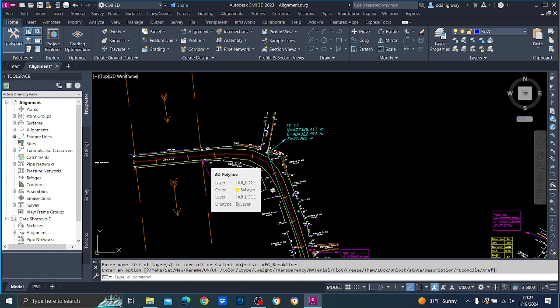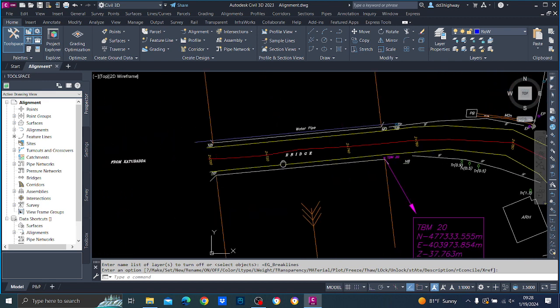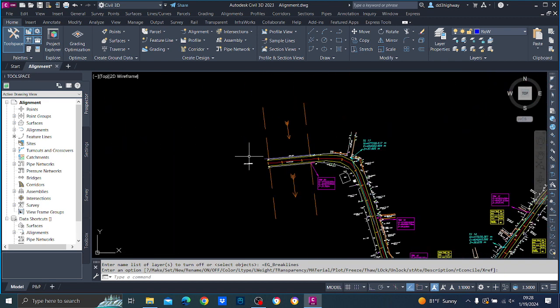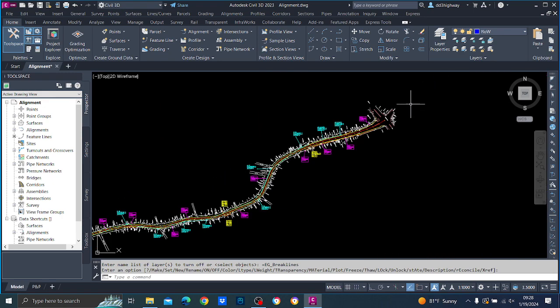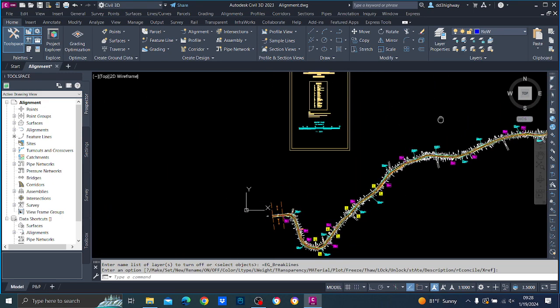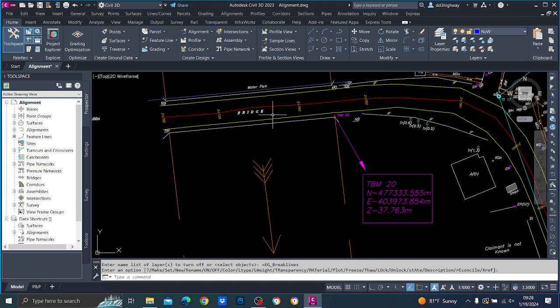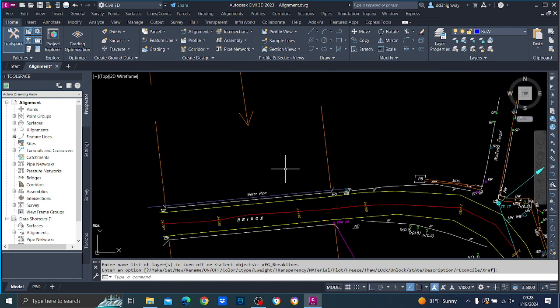But one thing you have to remember is to have in your mind the design speed that you are going to design for. So for this one, I propose 50, because what is this road? This is from Moratuwa University to Piliyandala Road. There of course this is some urban area, so maybe we can go for 50 kmph, not 70. This is that famous bridge. Right, so we will start designing.